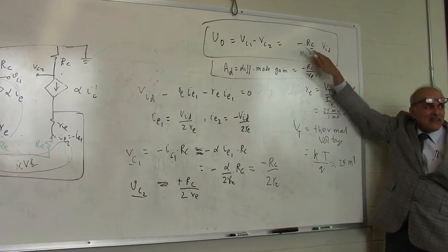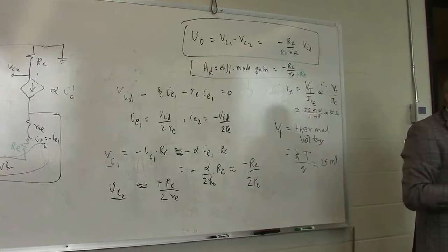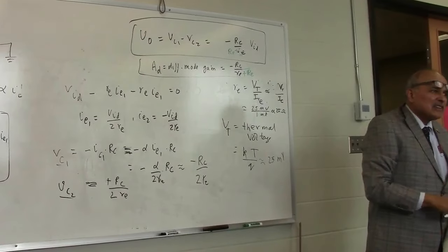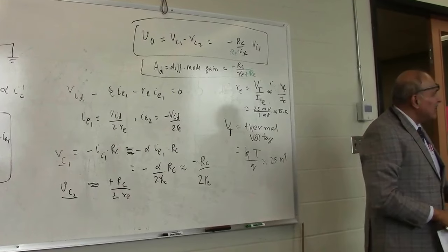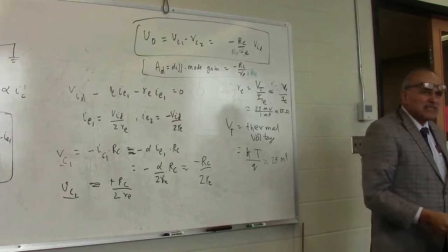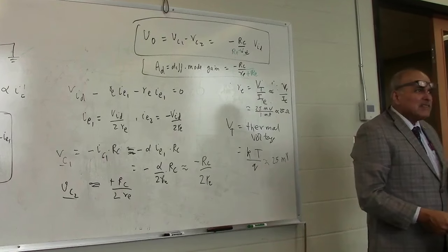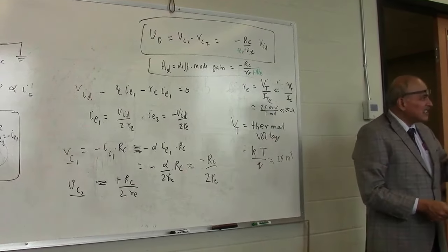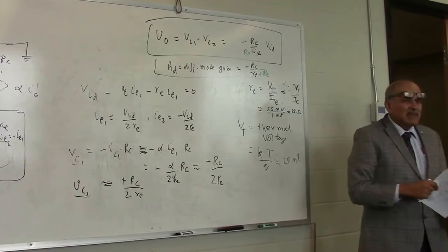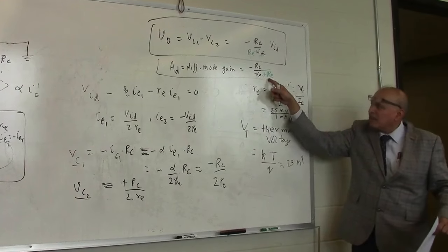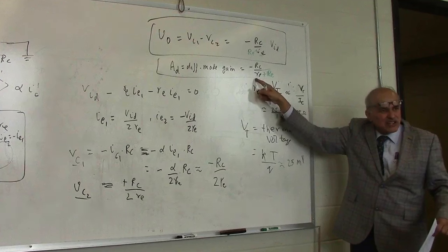And that makes your circuit independent of the characteristics of the transistor. Remember, in electronics, we get very sloppy components whose gains and performance can vary, and yet we make excellent circuits that give predictable behavior. By putting an external resistance yourself, you minimize the variation here.